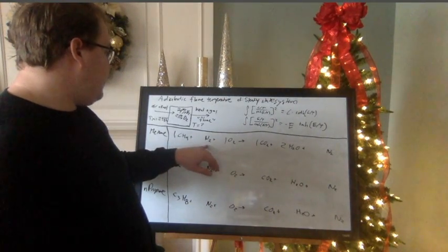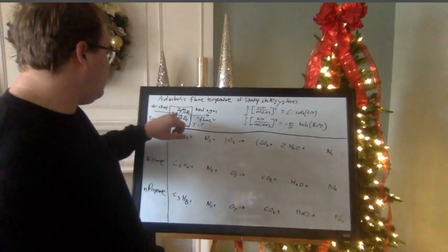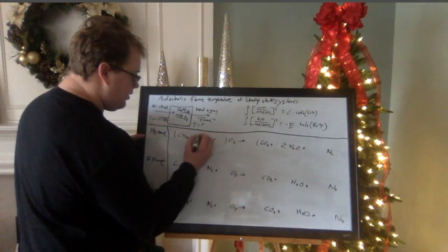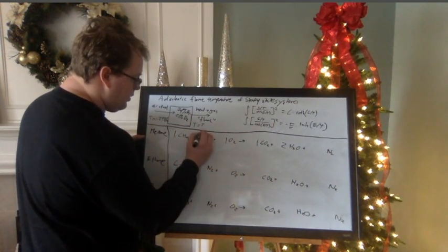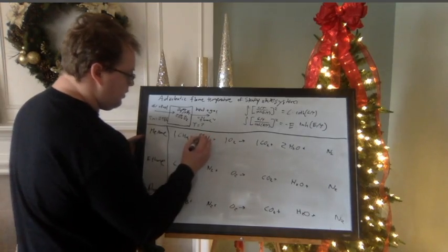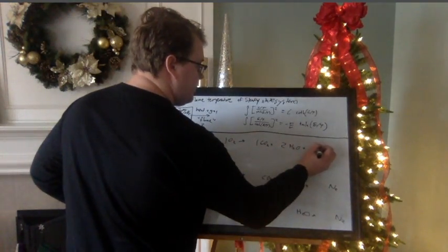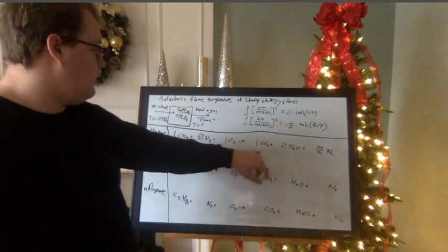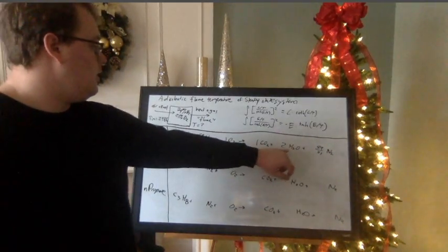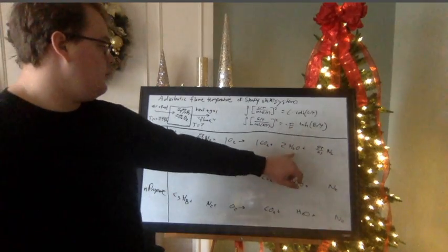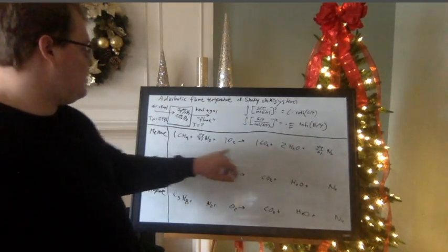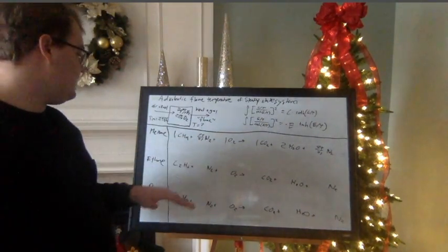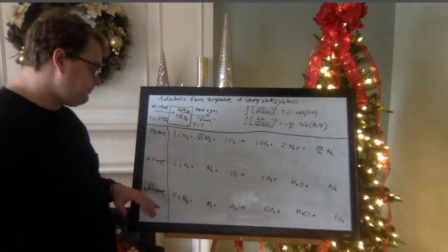And with respect to nitrogen and oxygen, I know I have 79% nitrogen versus 21% oxygen, so I'm going to take my nitrogen and do 79 over 21 on my left side and 79 over 21 on my right side. So just double check, 1 carbon, 4 hydrogens, 2 oxygens, 2 oxygens, 79 over 21 nitrogens, and 79 over 21 nitrogens. I'm done with the methane part of my fuel. This is balanced. So moving on to my ethane, I'm going to do the same thing.